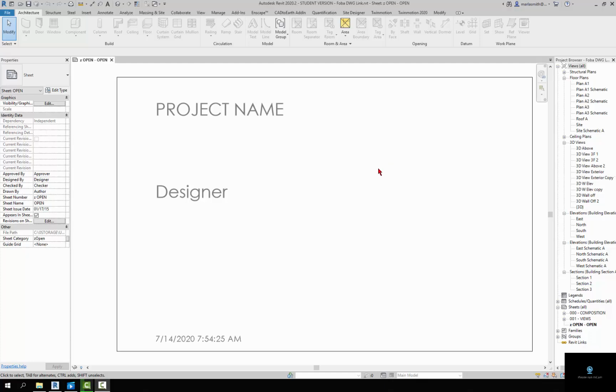And just in case I haven't mentioned it, I think I did mention it in the beginning, in order to get section cuts, you have to have closed poly surfaces from Rhino or whatever program you're using. They have to be solid mass. So this is a Rhino file of closed poly surfaces that has been exported to CAD.